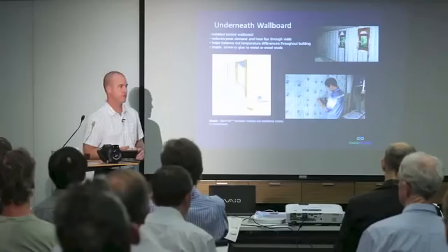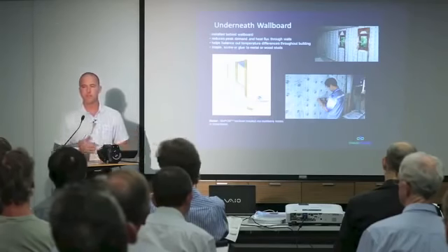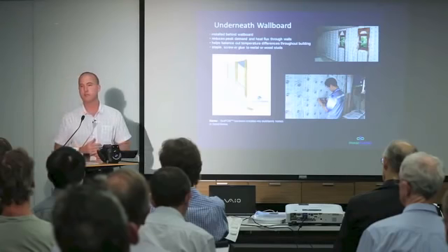That's expensive, which adds cost to the taxpayers, and adds cost to the new land being released. So what we're doing in Queensland is using solar panels on the roof to run the air conditioner while they're at work, which is free electricity. We pump the heat out of the phase change material in the middle of the day and get it down to 20 degrees. They get home, turn off the air conditioning, and the house is pre-frozen at 20 degrees, ready for them to enjoy their night. So it's free cooling in Queensland, much better than paying the 38-cent shoulder tariffs they have now.